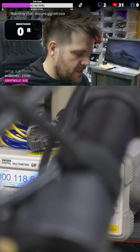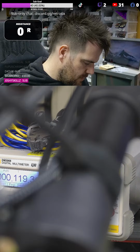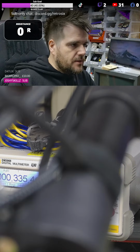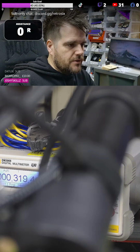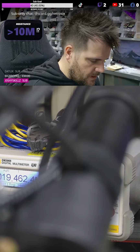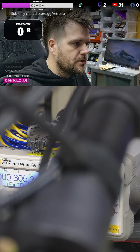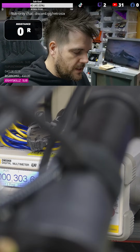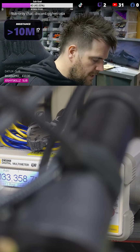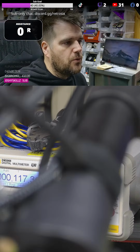So 0.1 ohms is on the actual short. If I move it over to the other side of the board, we're getting 0.3 through the wire. And if I probe on the inductor pad, yeah, 0.3 again. And if I go to the actual location of the short, we're getting 0.1.